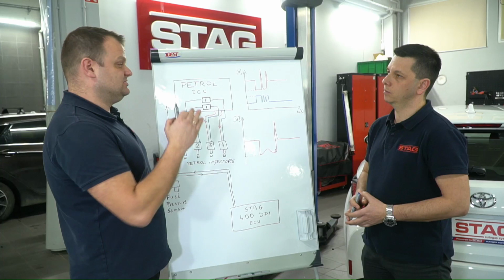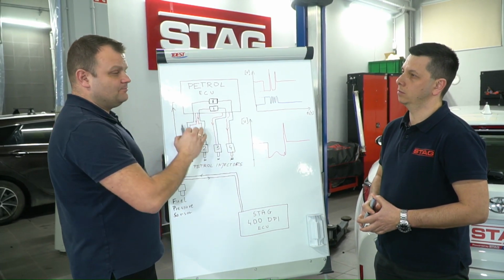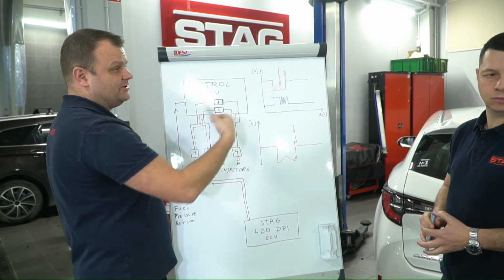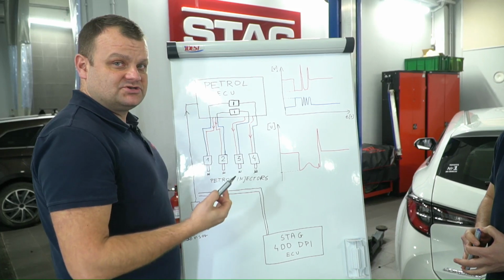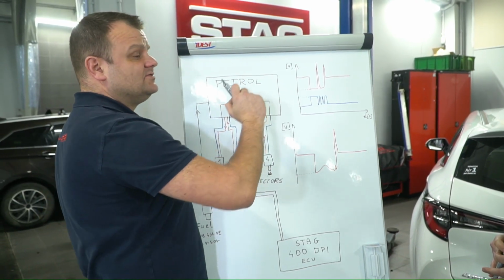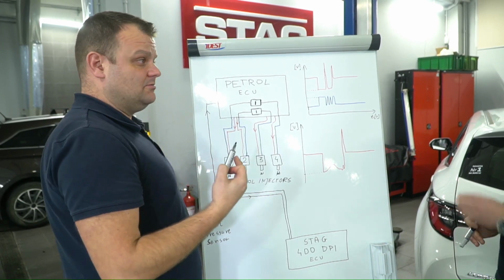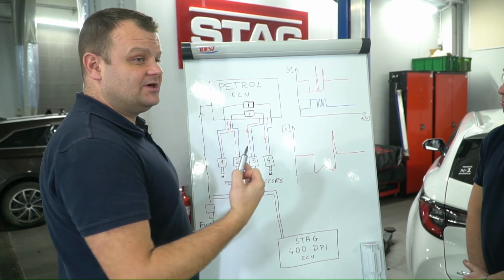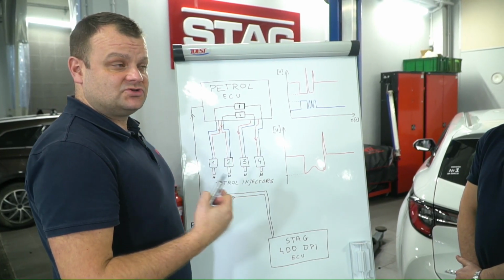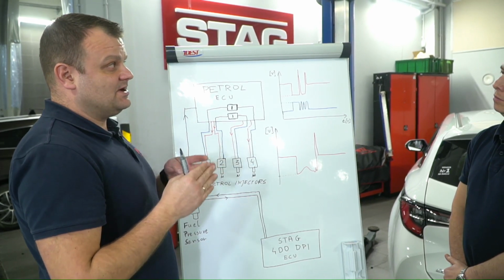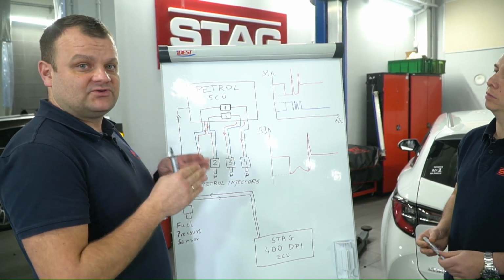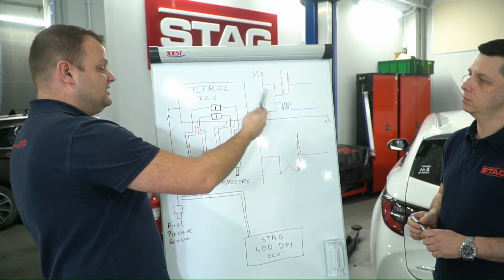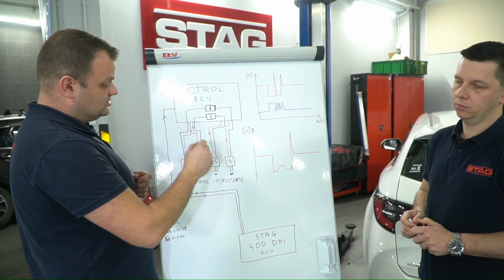And because of this type of power supply and the untypical signal compared to port injection engines, this is a kind of steering like a peak and hold. Yes, there is high control related to the opening time of the petrol injector to achieve as much precision in petrol dosage as possible. And because these signals are related to high voltage, we also have noise in the system.